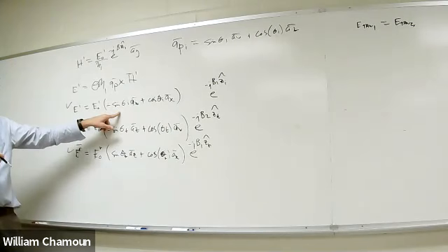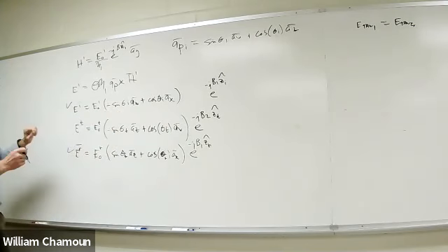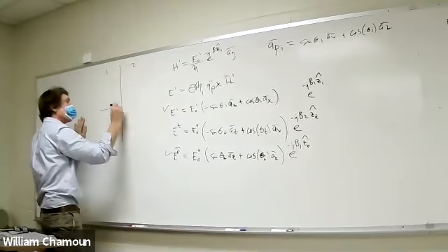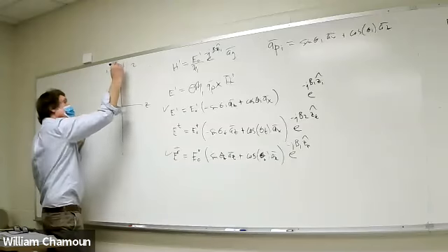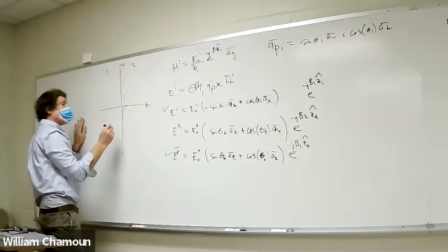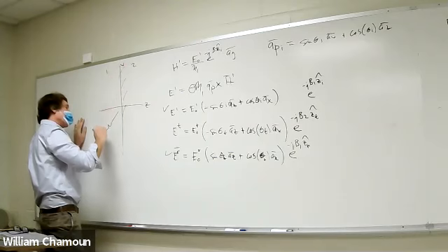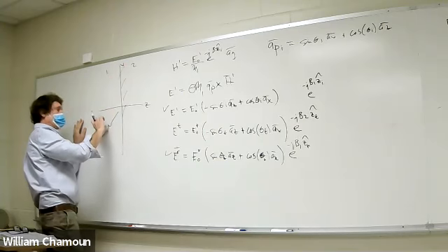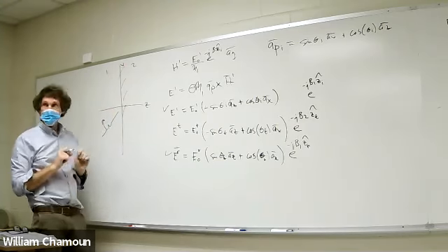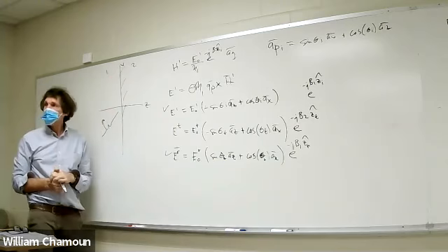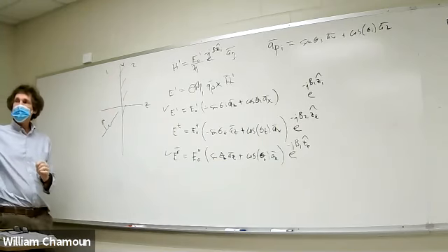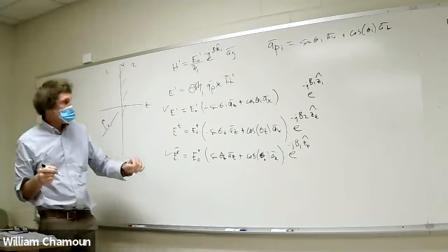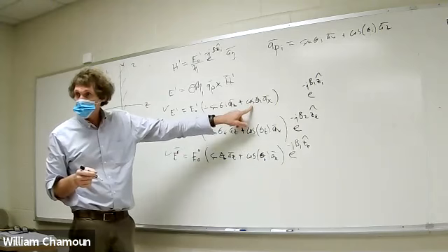If you're talking about the tangent E field, think about that boundary. This is region 1, 2. That's Z, that's X. Here's the boundary, right? When I take a look at the propagation, the E field itself is in this direction. If we wanted the tangent component of that E field, that would be the X component, wouldn't it, class? Can you see it? Are you good with that? I'm glad you're keeping me straight on this stuff. So the tangent component would be the X component, which would be this one, wouldn't it?